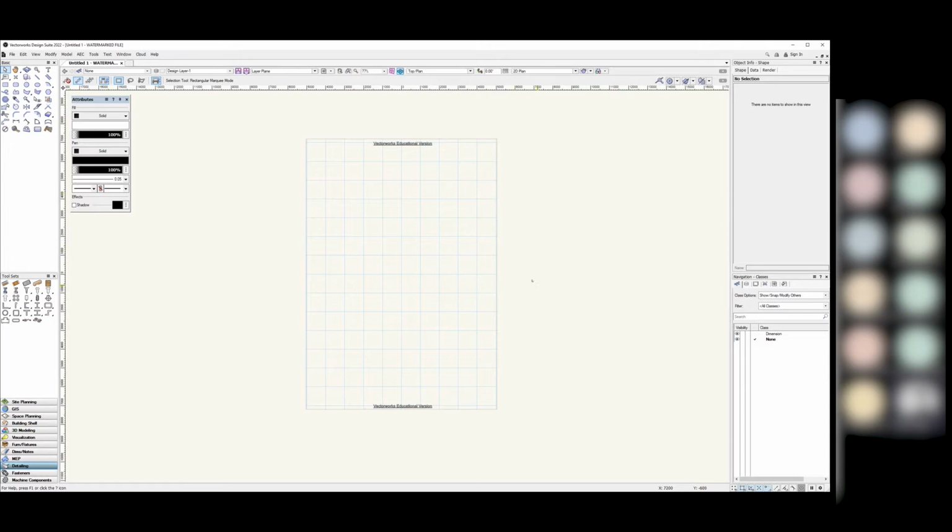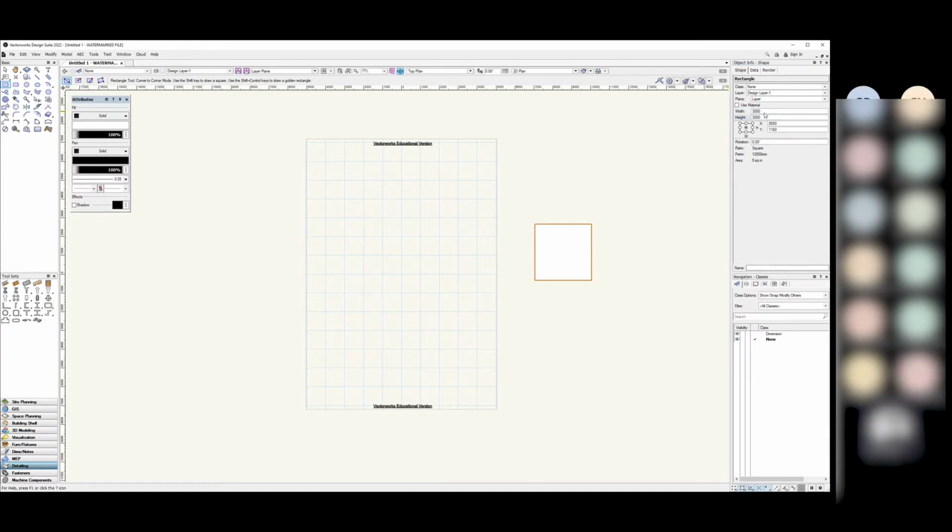Because the thing that people tend to struggle with here is understanding scale. So for instance, that shape that I had just now, you know, I could type in dimensions into this. I could type in 3 meters by 3 meters. If you're an architect or architecture student, typically we're always going to work in millimeters in the UK because we're using the metric system. If you're watching this in America, if you somehow found this video, you might want to use the imperial system, in which case you'd be working in inches. And again, I'll show you how you can configure this stuff in a minute.